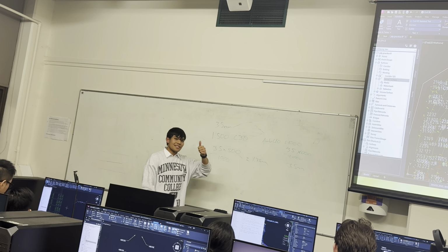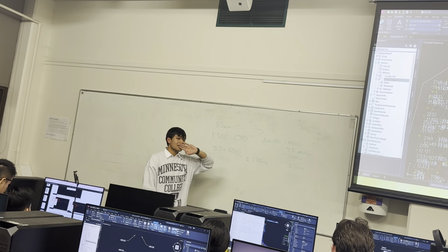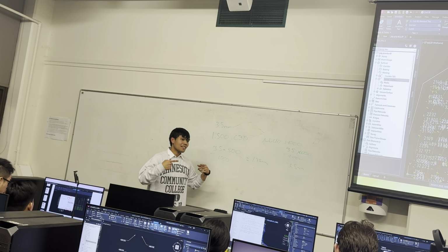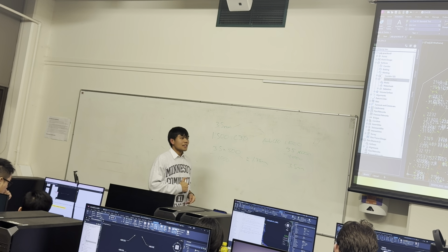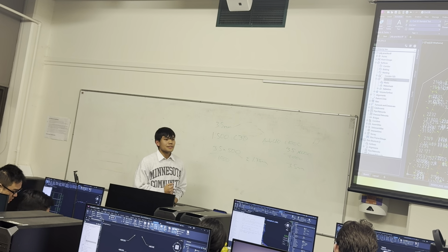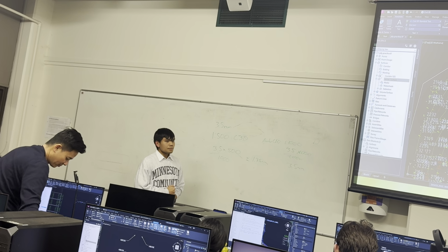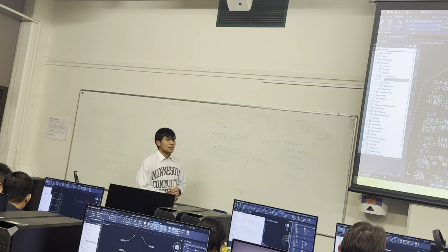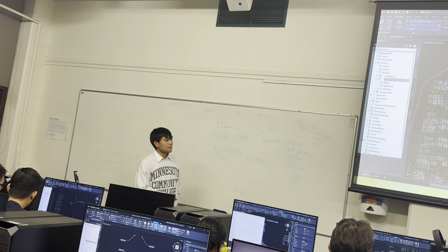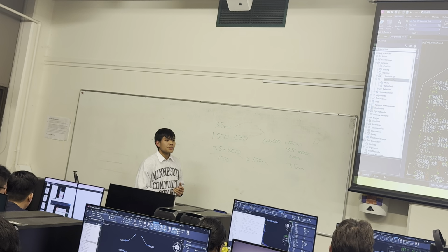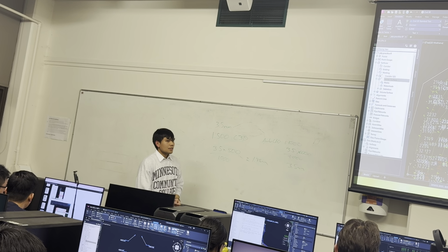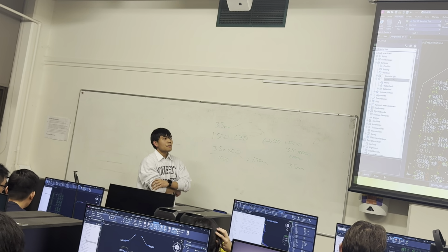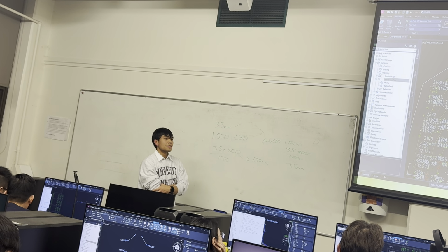Just a thumbs up if you guys got that. Do you want me to explain? So when we draw it on there, make it 1.65, for the labeling, yes. And then if we export it to AutoCAD, if we don't change the formatting, it will go ×2 bigger. It'll automatically be changed, because AutoCAD is naturally 1 to 1000. So if we make it 1.75 on here, it'll be the correct thing for this drawing.